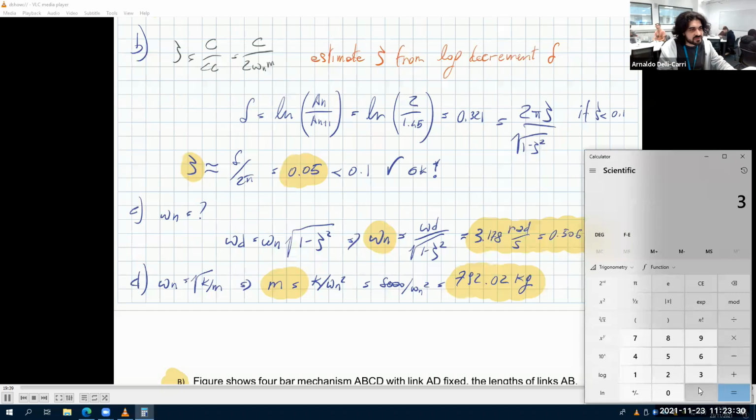So it's 3.178 squared, inverted, times 8,000. 792.10. If you calculate omega n, omega n equals omega d over the square root of 1 minus zeta squared. Omega n is this 3.178. I think the solution says omega n is nearly 20 radians per second. It's 19.97 radians per second.